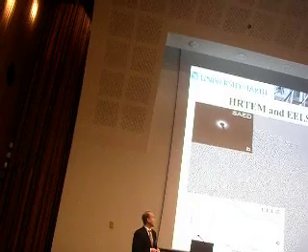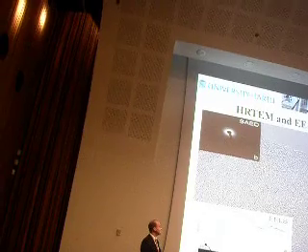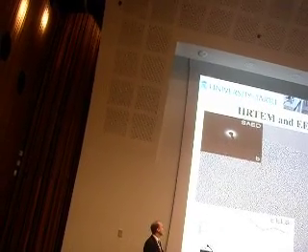Now also what this material looks like. The material that was synthesized at 800 degrees, we can see that it's mostly amorphous, like scrambled eggs. There are no graphitic lines that are visible, and also the selected area electron diffraction shows no rings that are specific to graphitized material.